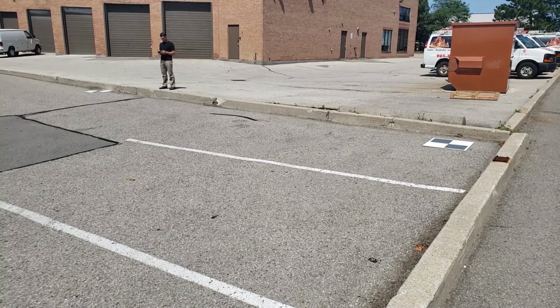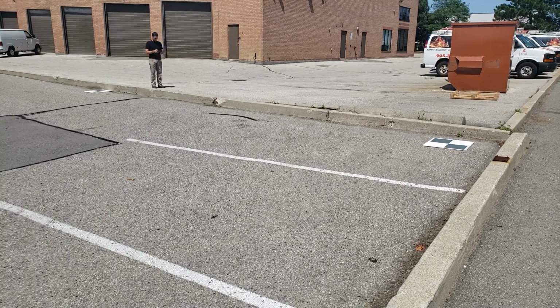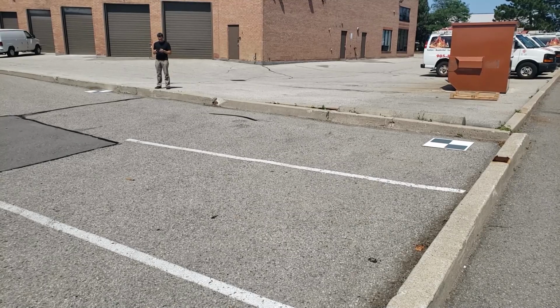And I'm going to come back a bit more. I'm going to overshoot this a bit. Now I'm just going to fly manually. I'm not going to do anything automatic here, so I'm not really concerned with the number of photos. I'm more concerned with how high I'm flying. So I'm going to try and keep this at 10 meters as best as I can. There we go. It looks like I'm getting these looking pretty good.